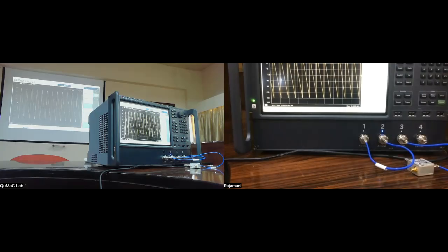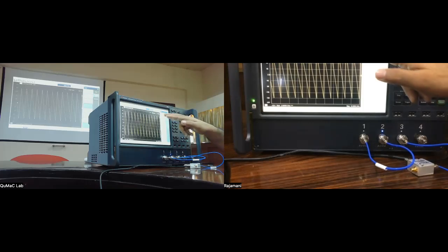So you see this thing called electrical delay. This allows you to dial in a number which will then basically trivially cancel out this particular feature, because it knows what the frequency is. Essentially, you're dialing in the length or the delta t. So you can enter them in both directions.